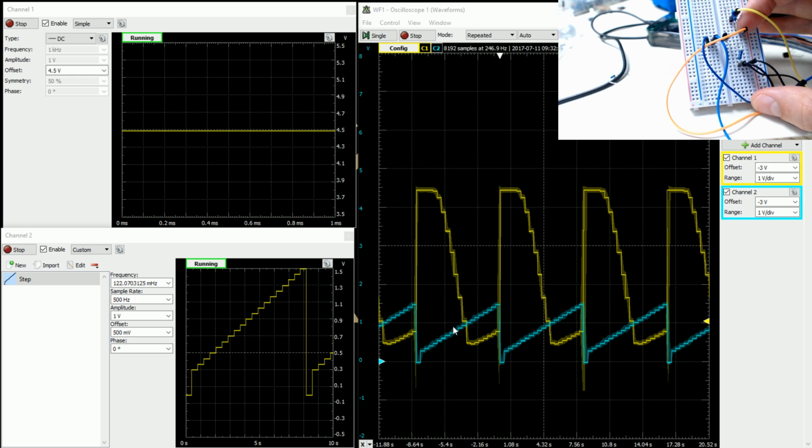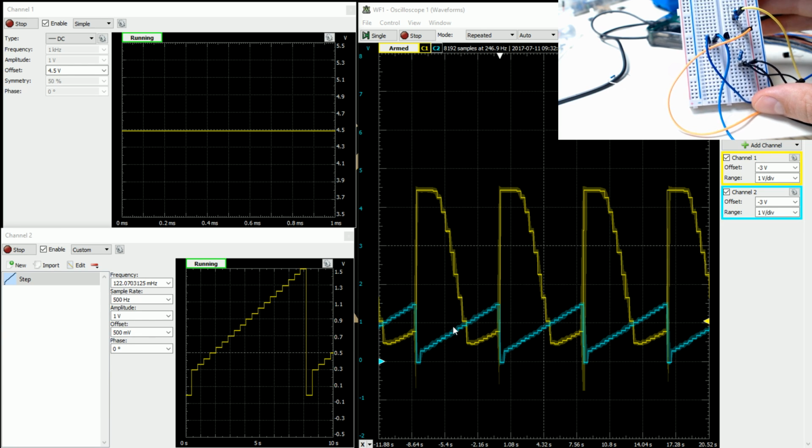And what we're basically doing is an IV curve for the whole thing here, right? So we're just turning on the transistor, and then we're watching what happens when we start to source current down through, this is a 10K up here, and then a 1K down here, right? So we're just looking at the amp, so it's not even the amplification, I guess it is being amplified, but you can see at the top here, when the transistor isn't turned on at all, there's no current flowing through the resistor, so there's no drop here, right?